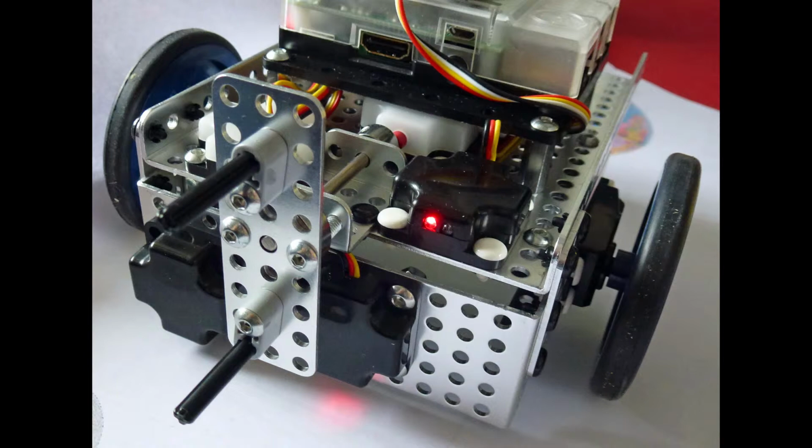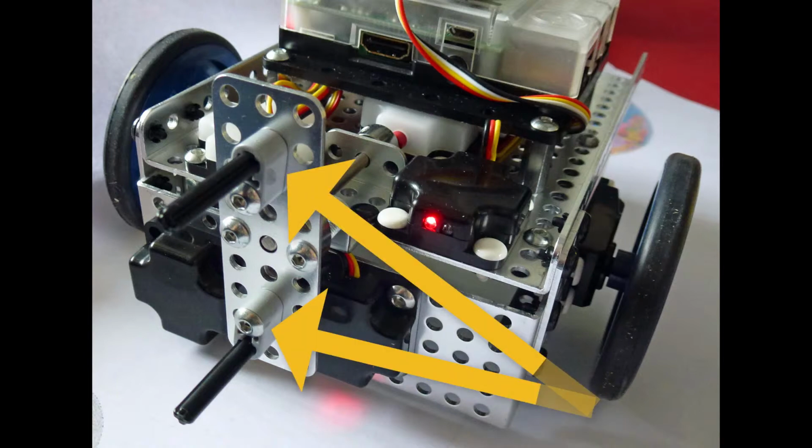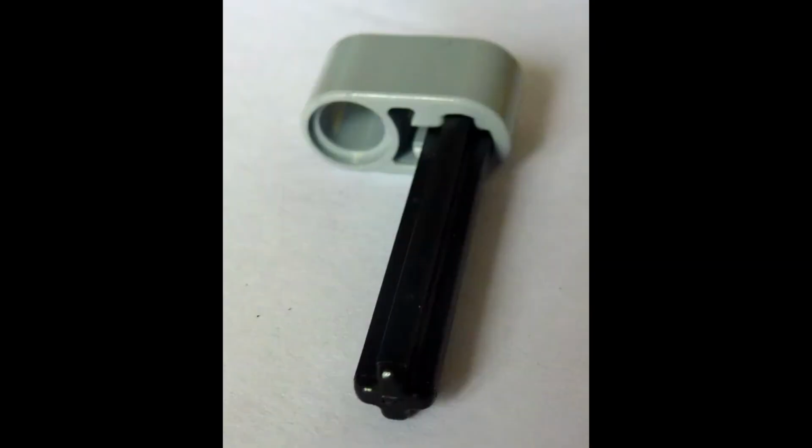And so we ended up having to add extensions to the touch sensor, as you can see here. This is the extension piece we needed to add to the touch sensor of our Fusion robot. You can see we used a Lego cruciform or cross-section axle, and it's about 3 centimeters or 1 3/16 of an inch long.